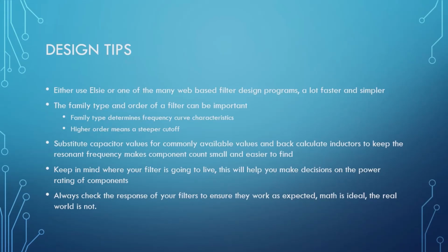Well, if you're wanting to use that at 4 megahertz, it might actually have a totally different capacitance. So that's why they always say you should use mica or NP0s, because those are actually rated to maintain their capacitance across the frequency band.